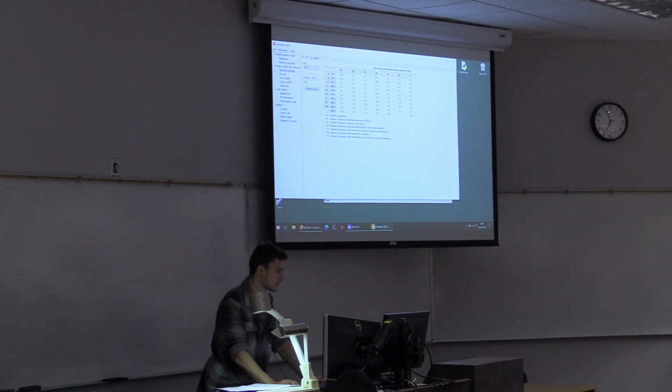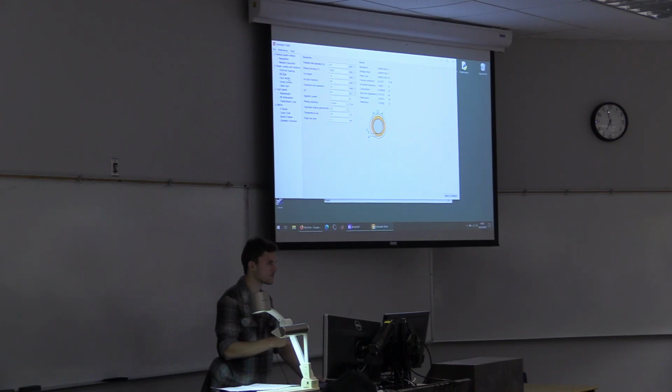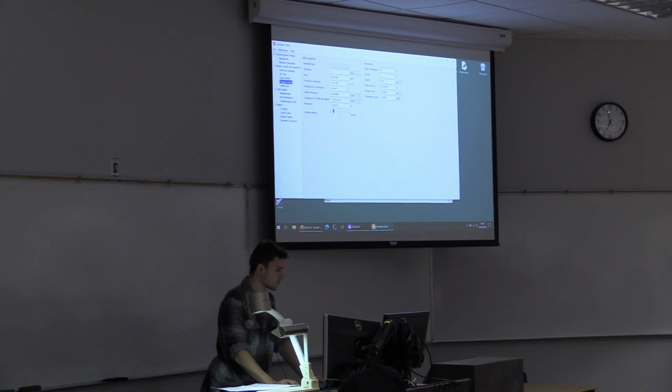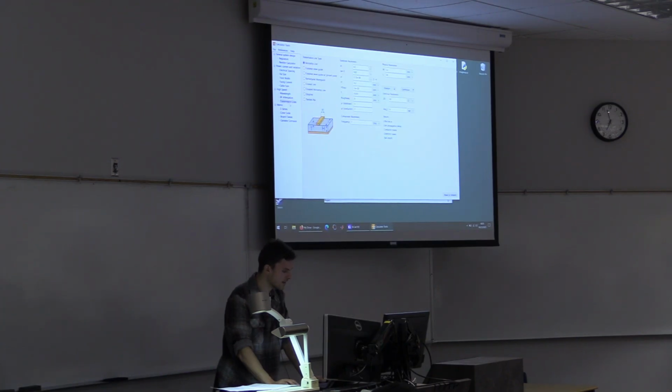Via sizing, most of the track width and via sizing, this is for if you want to run a good amount of current through them. You want to size them correctly so they don't heat up too much. Additionally, there's some impedance stuff for RF. And then we've got the track width, fusing currents, cable sizes, a whole bunch of stuff, even transmission lines. So that is a fun one.